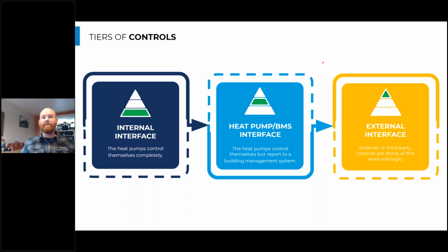And there can be great advantages to integrating our heat pumps with a building management system that's already in place, or potentially specifying a very minimal building management system that is just looking at our outlet water temperatures from our heat pumps and any alarm conditions, as well as the outlet water temperature to the building fixtures. Knowing a few points just like that can really be an advantage to our building maintenance personnel, so that they can be more proactive on keeping tabs on these systems and making sure they're running really efficiently and effectively.